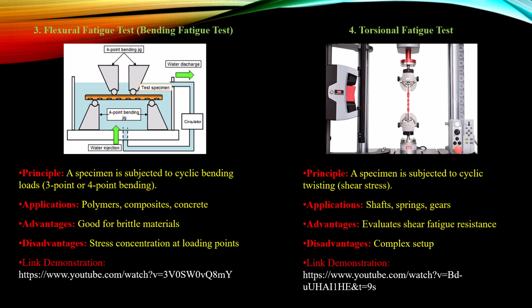A key advantage of this method is its ability to assess shear fatigue resistance, a critical property for rotating or twisting components. However, the test setup tends to be more complex compared to other fatigue testing methods, which can increase preparation time and costs.